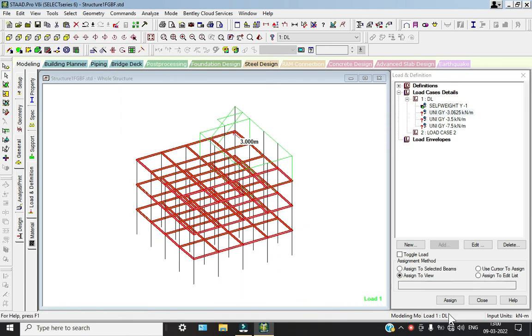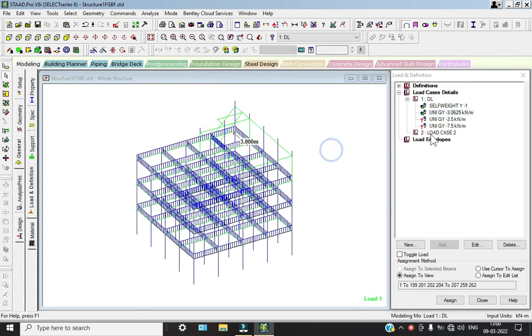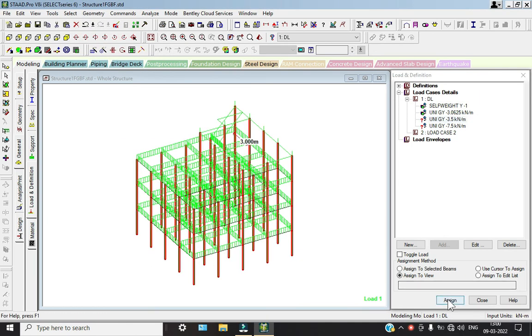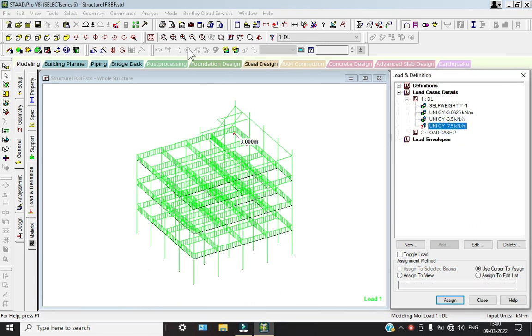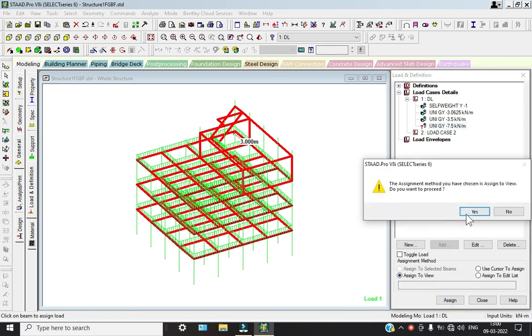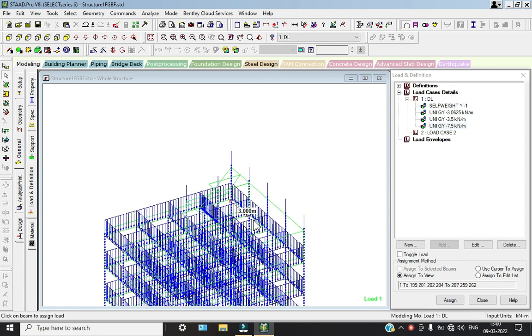So okay, now we will go to the none load, click on add, take the plate loads, select the hydrostatic ones. So here you have to select the plates, right? So for that go to our front view, you have to select all these plates. What we have selected, right? So we have to select all the plates over here. If you go to 3D, so unselect this one, so it will be acting over this only, right? Click on OK. So direction of pressure is GY. So we're going to